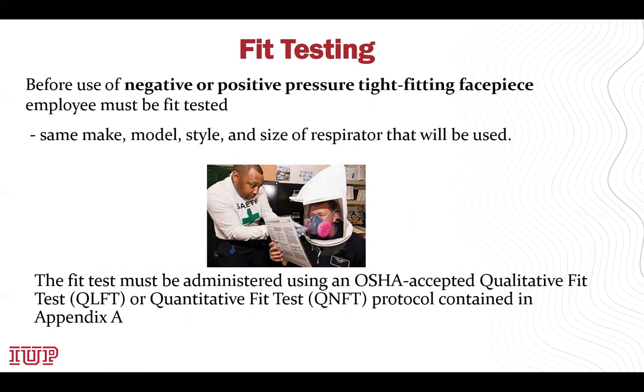Before using a negative or positive pressure tight fitting facepiece, the employee must first be fit tested. You want to use the same make, model, style, and size of respirator to be fit tested. The fit test must be administered using an OSHA accepted qualitative fit test, QLFT, or quantitative fit test, QNFT, protocol contained in Appendix A.